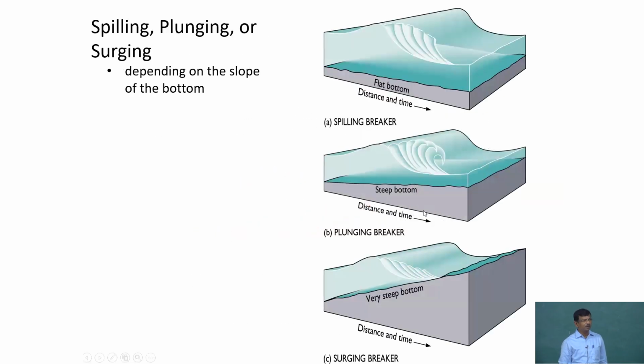Now, wave breaking we can classify predominantly into four types: spilling, plunging, collapsing and surging. Spilling is what we most often talk about in the deep sea, where the water depth is sufficient, finite or deep water depth. Plunging is what you see at a surfer's paradise, where surfers love to surf across the plunging waves.